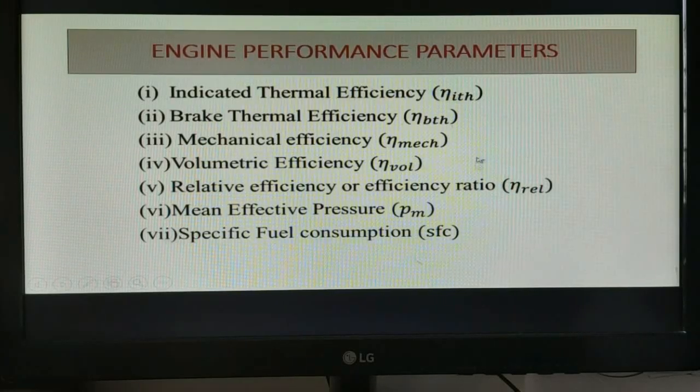So for any engine, when you are finding out the performance parameters, you have to find out what is the indicated thermal efficiency, what is the brake thermal efficiency, what is the mechanical efficiency, what is the volumetric efficiency. Depending on all this, we'll be testing the engine.